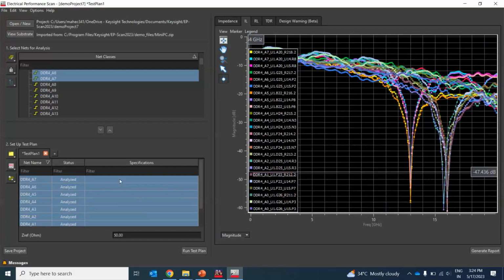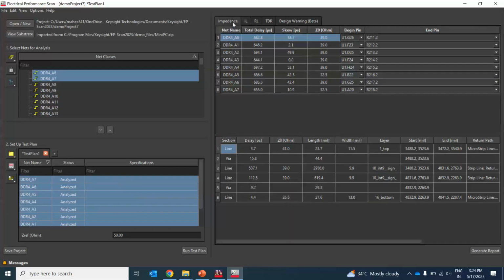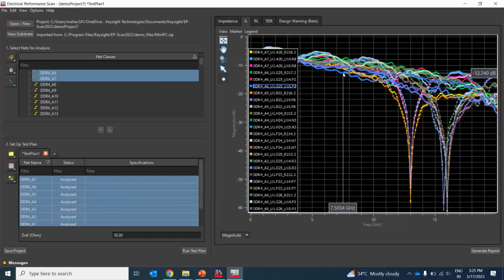So you can again check this against any specifications as well, like any DDR, PCI. And at the first instance, if you don't achieve the impedance target, as a layout engineer I have the flexibility to go back to my board and tweak the line parameters. If I don't match the impedance, I can change my width, reroute, and update back to the analysis here.